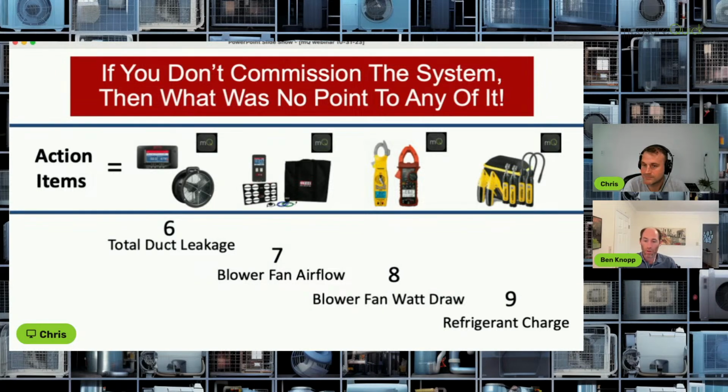So we also are adding ventilation to this home because when we air seal it, we need to make sure it's ventilated. Well, for this home, we calculated it needed about 92 CFM continuous of ventilation air because there's 6 people in the house. And that's 10 gallons of water a day coming in just from the ventilation air.